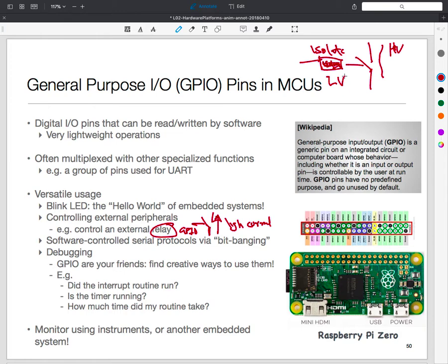There are other ways of making this happen, but if in your project you venture into things where you're controlling something which is high current, let's say something to do with home automation, then either get a relay which already has the isolation in it, or make sure you provide the isolation. Okay? Very important to keep the two separate, because you don't want to get electrocuted.